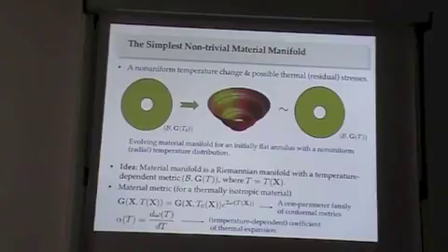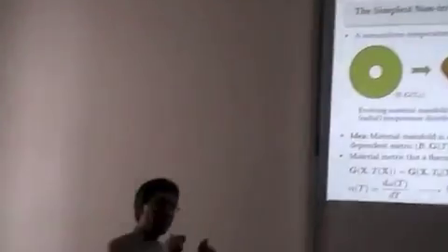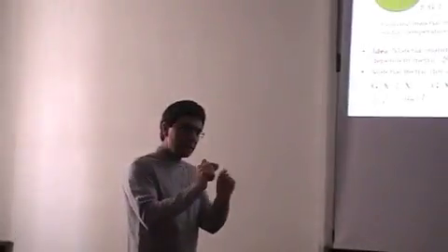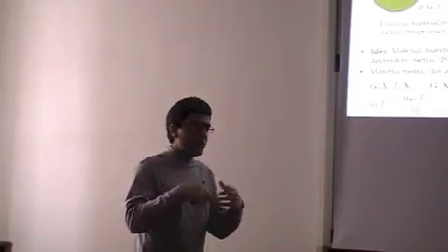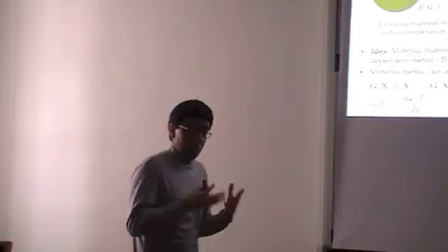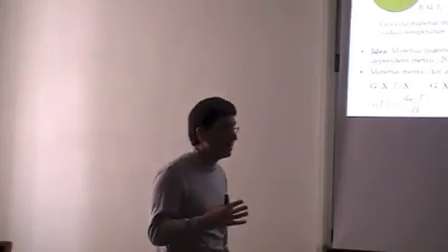Now, this is how I define my material manifold, where I'm stress-free by construction. So why do you induce residual stresses? Your natural distances for these two points, after I change my temperature, become something like this. And because these natural distances vary from point to point, the rigid geometry of our two-dimensional Euclidean space cannot support that.